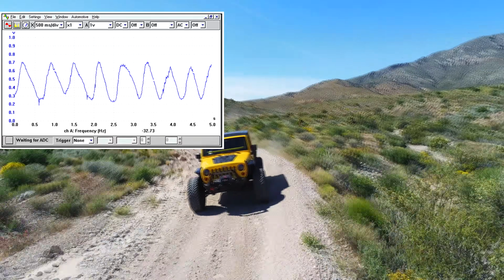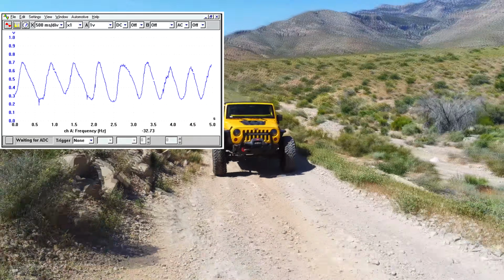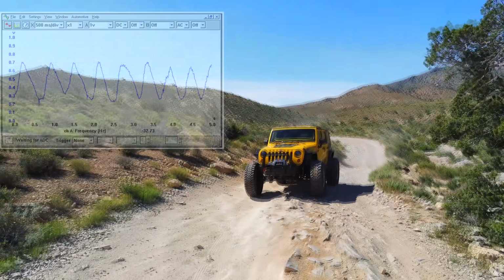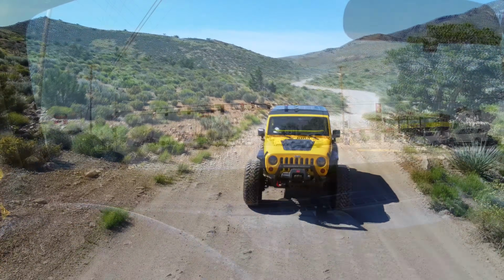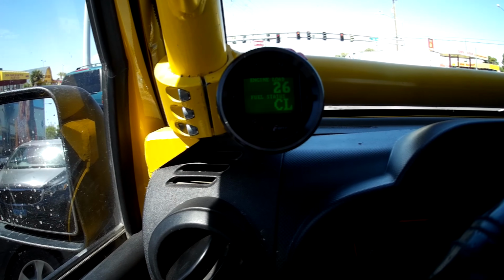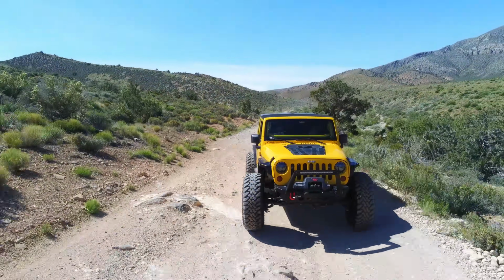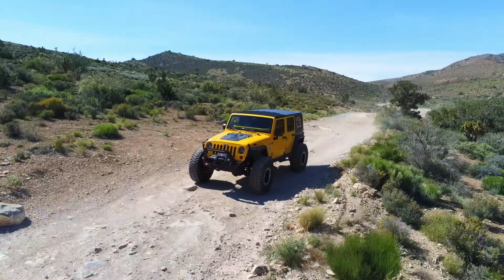You drop below 0.450 volts. Now you're lean, and the operating system knows that, so now it commands a rich command. This is what ends up in the switching of the O2 sensor around stoichiometric, up and down, up and down. That is closed loop operation, and that's what this is indicating right here. Right now our engine load is low because we're idling. We do have the air conditioner on. So in a perfect world, we would like to be in closed loop all the time and run at stoich.